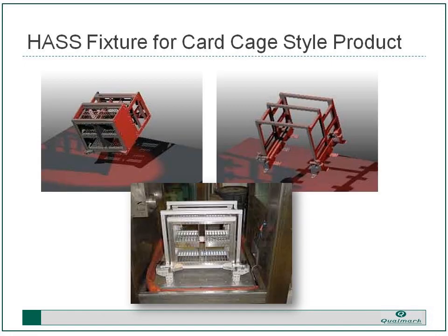Now, one of the unique challenges that you can run into is designing a fixture when you have a product that is essentially a card cage with a bunch of cards plugged into it and a motherboard in the back. Often, a product that is in its final configuration like that, a motherboard with daughter boards plugged into it, if you try to test that product assembled, you'll find that you get very poor vibration transmission into the boards inside. The product isn't a very good vibration fixture.